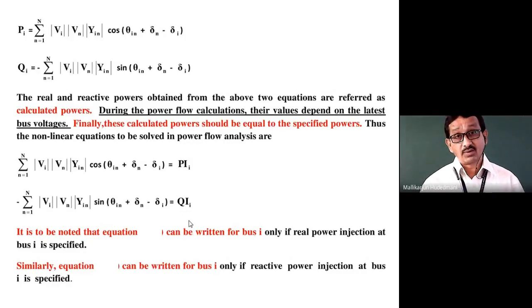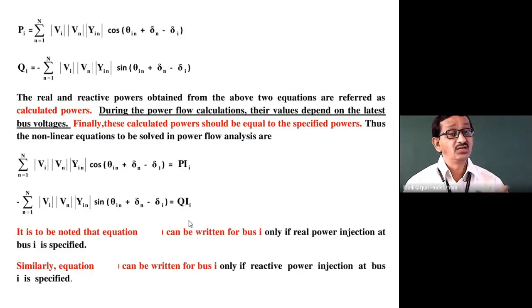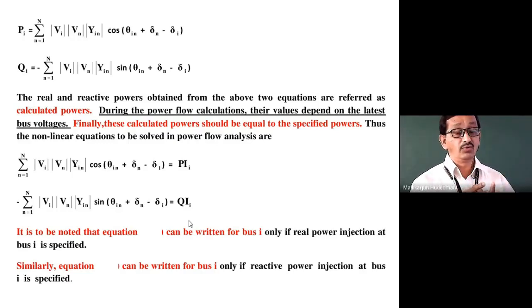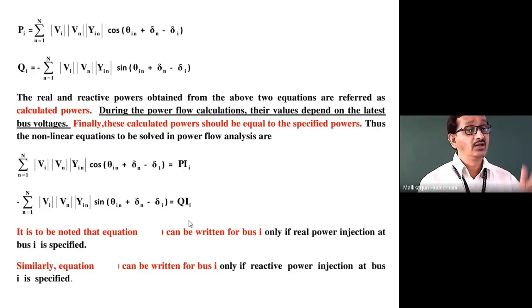So this way, the power engineer will come to know from the load flow study and steady state analysis whether the system is stable or not stable. If not, what other measures one would take is then considered. Therefore, we see these equations are the fundamental load flow equations. Now I am viewing them from the load flow analysis of NRLF, the Newton-Raphson load flow technique. Then I will be using the computed active power and computed reactive power from the basics as the injected active power and injected reactive power of any bus I.